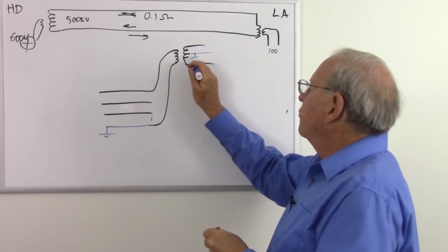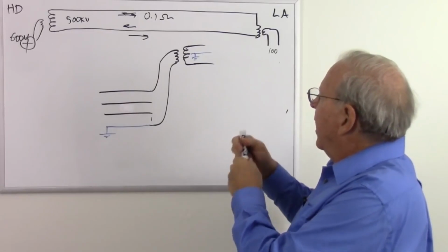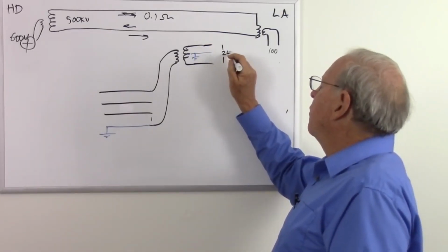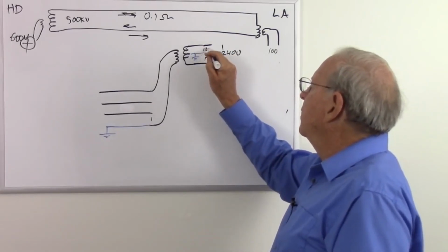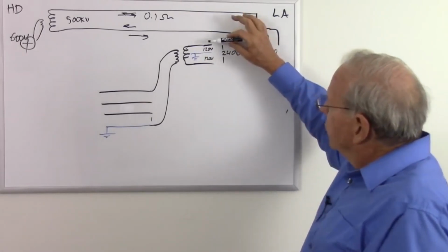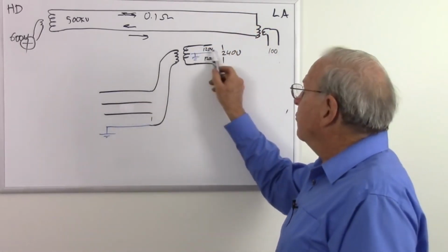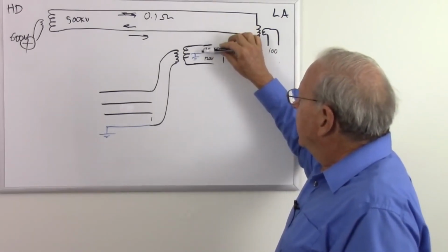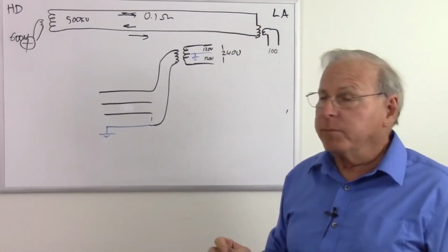That's going to be grounded somewhere so that it's referenced to ground. There's our neutral wire, and this is going to be a total of 240 volts or 120 volts on each phase. So when we get the single phase, which is the norm in residential wiring, it will be what they call split phase, where you get 120 to neutral, 120 to neutral, or 240 across both.